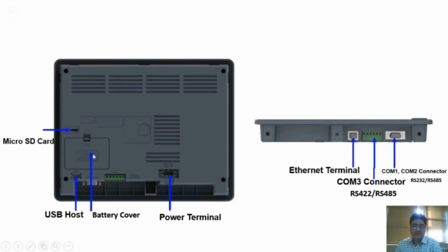This subsequent section is specifically about the protective battery cover, because the HMI unit itself has an internal replaceable battery accessible by removing the cover. DIP switches allow configuration per the HMI manual. This relates to the device's own dedicated power supply, which can be either a 24-volt direct current DC or a more extensive range of 110 to 220 volts alternating current AC.